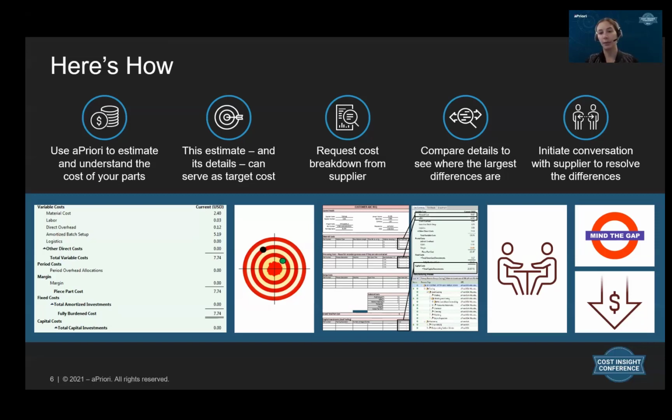I had a supplier whose labor cost was high because they were manually masking off parts when they did conformal coating, but we were assuming they were using masks, reusable masks. And so we split the cost of reusable masks and we reduced their labor cost for future builds. It's a cost savings for us both.